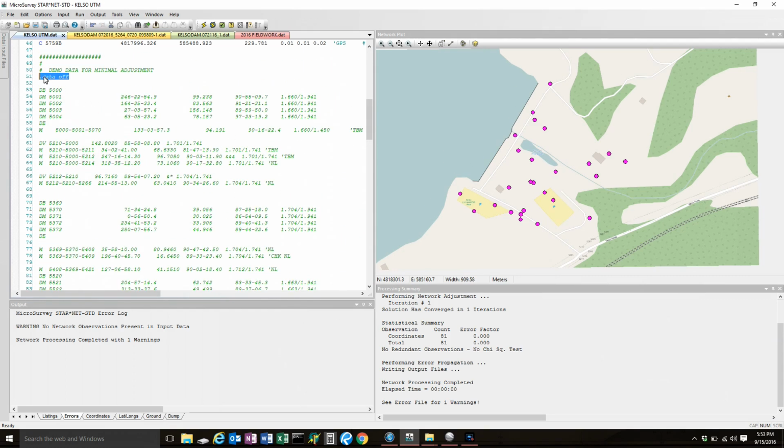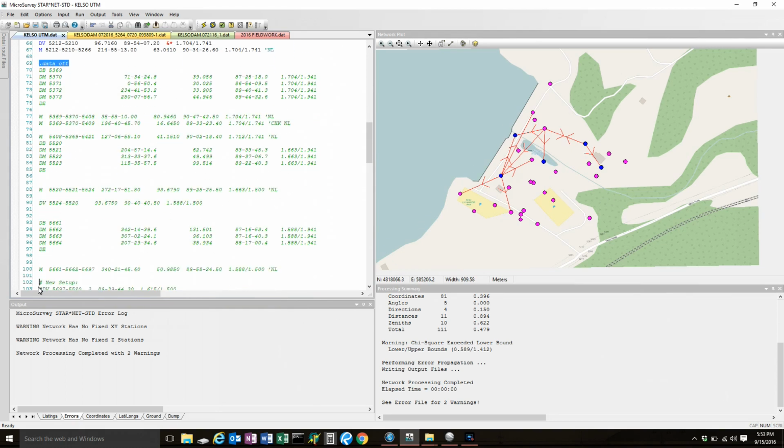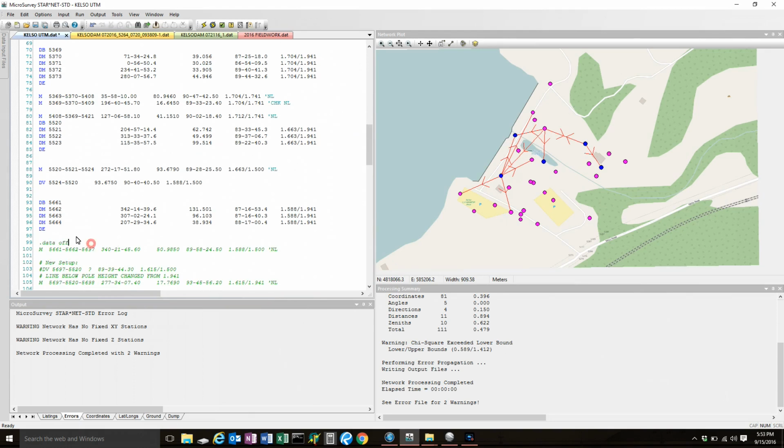So here's my first resection. I'm just going to simply move that, get onto there, save, and rerun the adjustment. And you can see there's the first part of the traverse. So there's my first resection. Traverse, I believe, went over to there. Then there's a check back to this point, and traverse extended over. If I take my data off line, move it down, save, and run, you can see now how my traverse is growing a little bit farther out this way, also out this way.